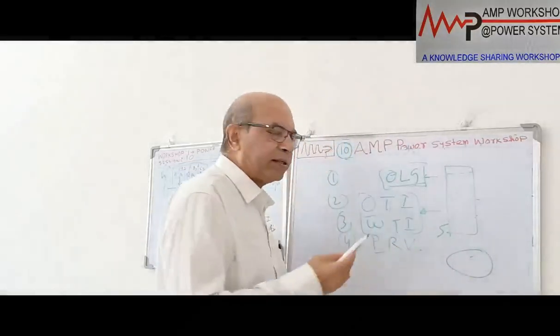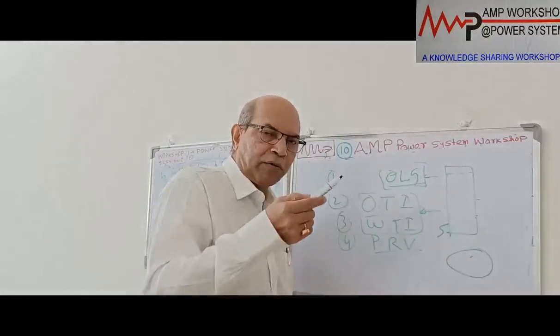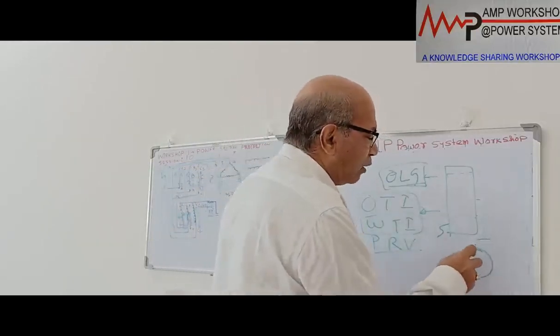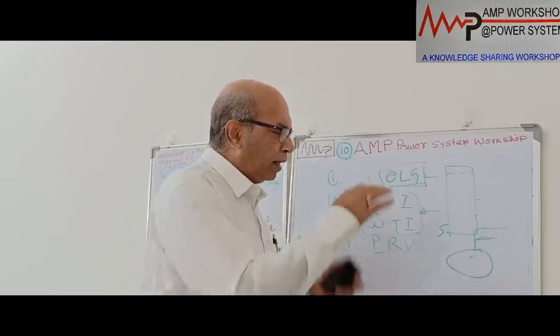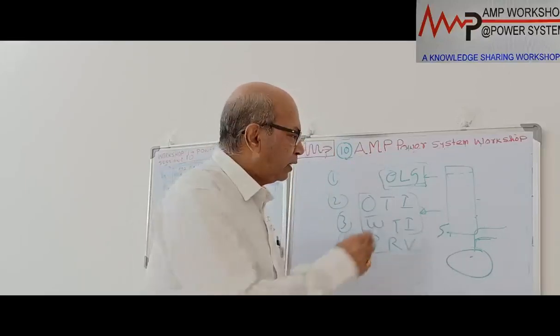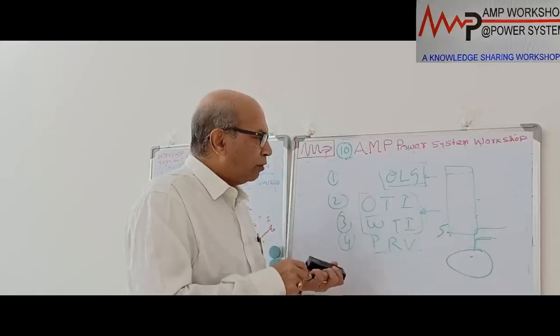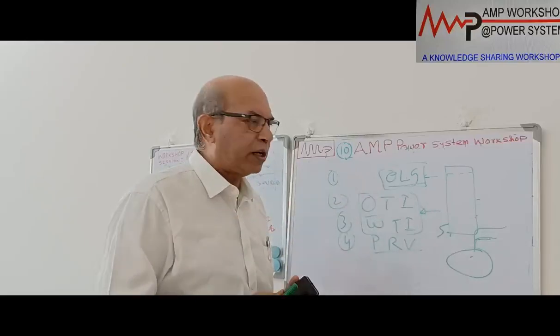This PRD device has a nozzle. It will get out the extra pressure by throwing out the oil, or if the oil pressure is not very high, then there is a pin, and through that it will operate, and then the extra gas or whatever is there gets out, and then automatically it will be reset. So these are the automatic devices installed with the transformer, coming with this transformer. So this can protect most of the internal faults of a small transformer of this size.